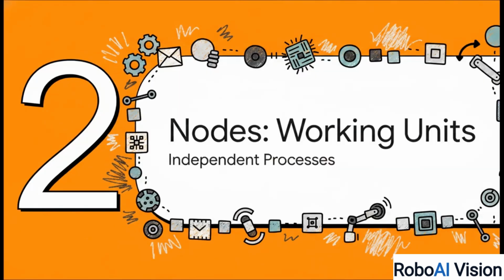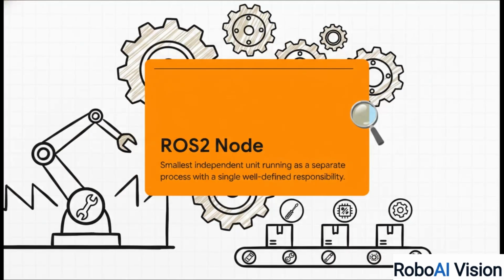Moving into Section 2, nodes as the working units. Let's dig into how the actual computing work gets done. In the ROS2 universe, the core processing unit is called a node. You can think of a node like a highly specialized worker on a factory assembly line. It is a completely separate executable process, and it follows a really strict single responsibility principle. It only does one job, just one, but it does it incredibly well.